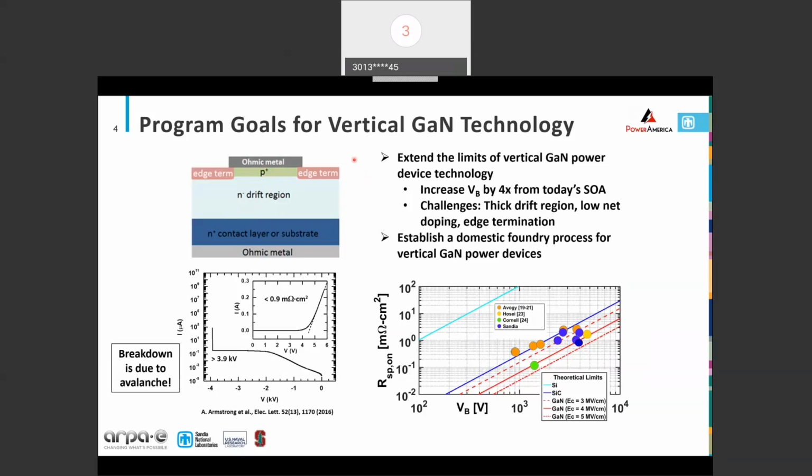And finally, I assume thermal management is not going to be very helpful for reliability as it is the case in GaN HEMTs. Is that true? In terms of thermal, you've got the thermal conductivity of GaN, which is what it is. You don't have a lot of the interfaces in these types of structures like you would in a HEMT. A HEMT is grown on silicon, it's got the strain management layers and so forth, and it's a pretty surface sensitive device. This really is more of a homojunction device.